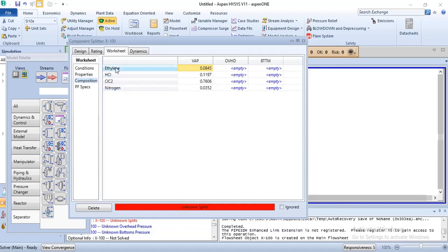Then the ethylene and the HCl are what is left after the process has taken place. So technically we are separating ethyl chloride from these three others, and that's why we are making use of the component splitter, so that it can separate it entirely without leaving any part of the ethyl chloride with the rest of the substances.